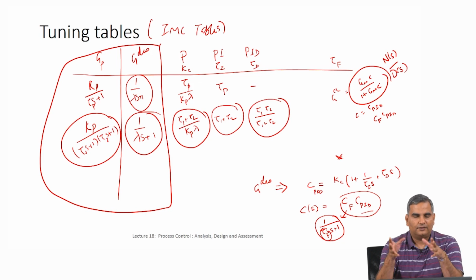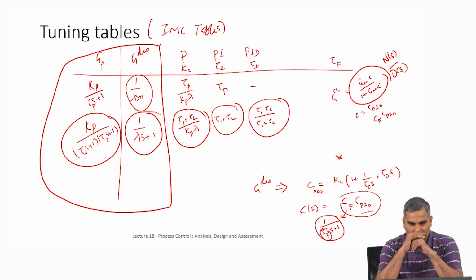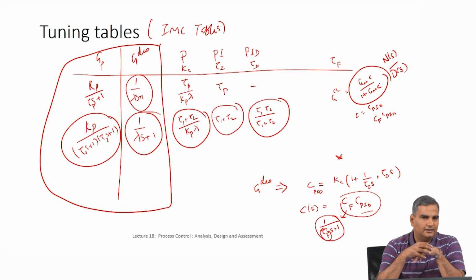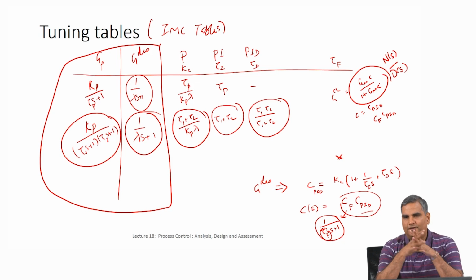And then we said if the denominator polynomial is in a root resolved form, then basically look at the roots of the denominator polynomial, which could be real or complex, and as long as all the roots are strictly in the left half plane, then we can say the system is what we called stable or bounded input bounded output stable, which basically means whenever I give a bounded input, the output will always be bounded if all the poles are strictly in the left half plane. So this is as far as the open loop system is concerned.